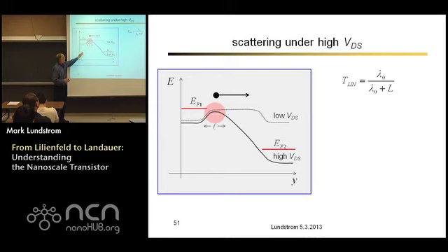Now we have a short region right around the virtual source, the top of the barrier. If electrons scatter there, they can return to the source. If electrons hop over that and start going down the electric field, it doesn't matter if they scatter anymore. It's irrelevant. The electric field is so strong, it'll sweep them out. It's like the collector of a bipolar transistor. It's just going to sweep everything out.